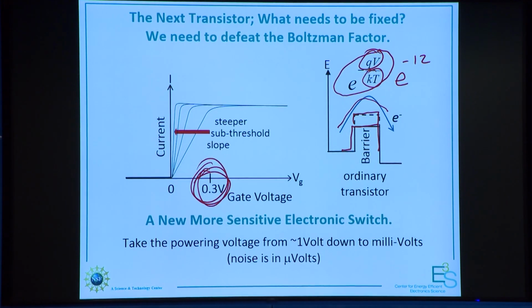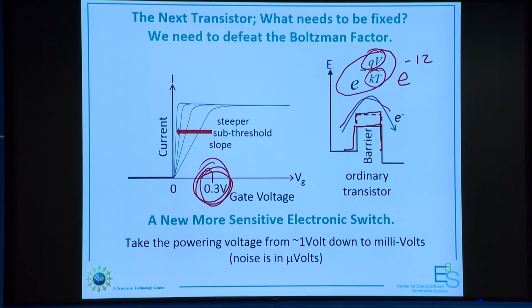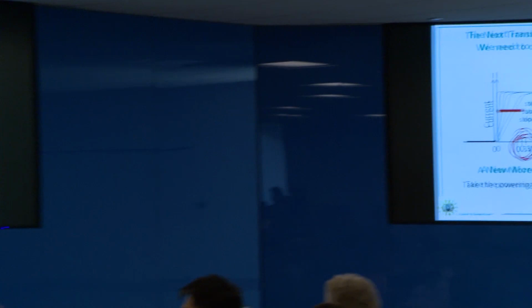So when it comes down to it, about 15 years ago, they kept reducing the voltage, they kept making progress, but they stopped improving the voltage much at all. About 15 years ago, if you bought a laptop, the voltage would be 1 volt. And if you bought a recent laptop, the voltage would be 0.9 of a volt. So there's almost no progress because you're fighting the Boltzmann factor, okay? And so the first thing you need to do is defeat the Boltzmann factor.